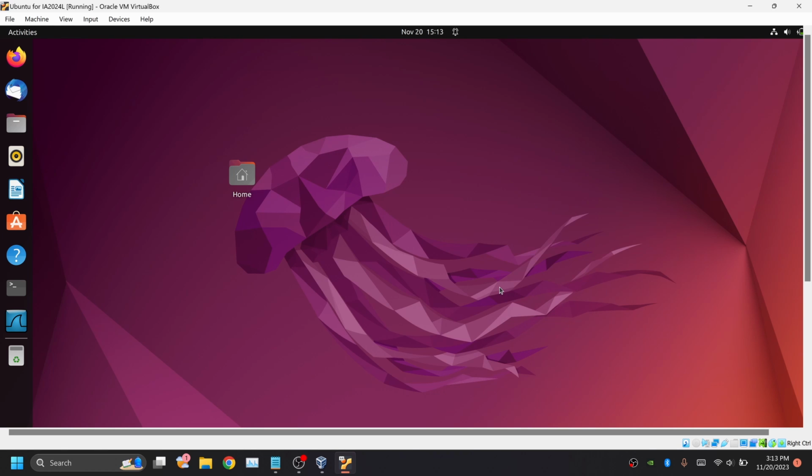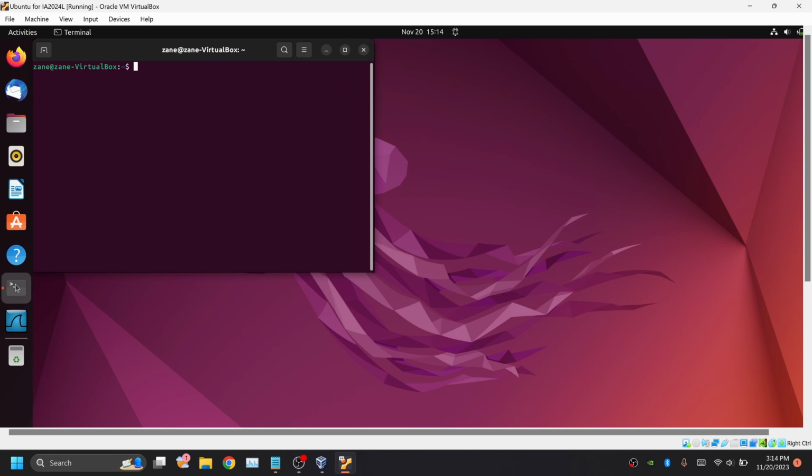Okay, so I wanted to do a quick demonstration of how the ICSim and CanUtils programs work together. It helps display how vulnerable a CAN bus system can be, and you can test certain things and send CAN frame data and so on without actually having to use a car, which is nice because I don't think anyone really wants to mess anything up in their actual car because it's quite expensive.